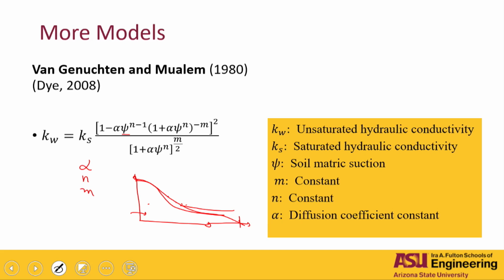Air entry value? Yes, ma'am. You're talking about the lambda value in the Van Genuchten hydraulic conductivity function model. Okay. This guy? Yeah, this guy, alpha.